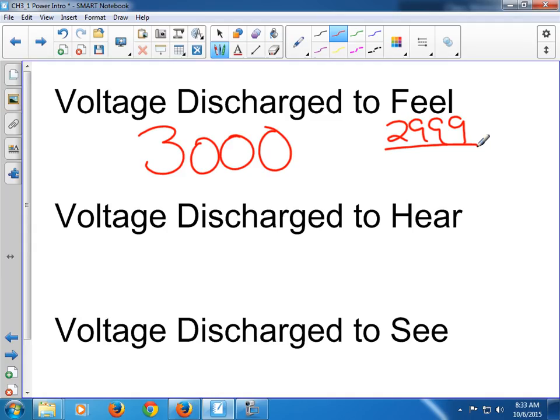Why do we touch the power supply first? Because it's used to getting all kinds of discharge voltage from the wall. This is a hardy component. It's the hardiest component, but it's also the one that will usually fail first. But it's not going to fail from our static electric charge. So we always ground ourselves to the power supply first because we might have this in us.